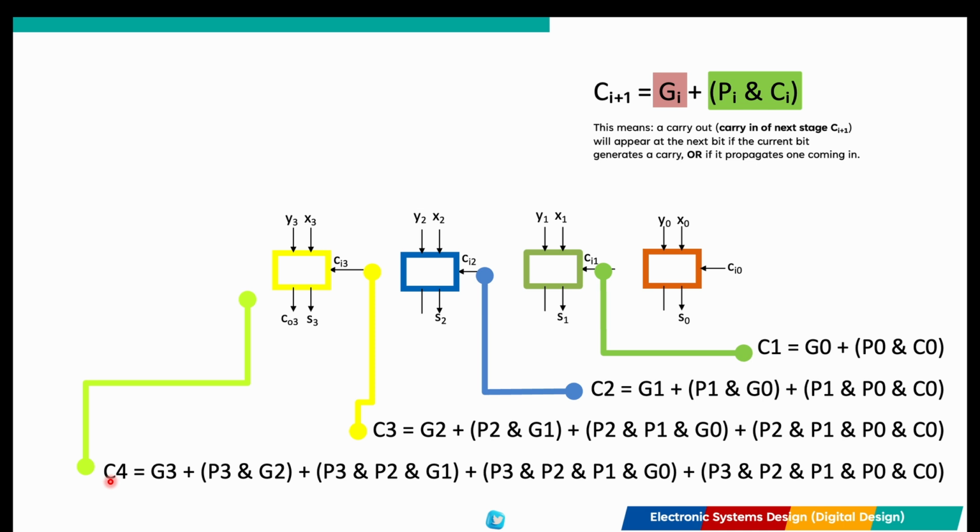Whether you are adding 4 bits or 32 bits, carry look-ahead logic ensures that the last carry is calculated almost as fast as the first carry. This is the core of performance-aware design. By spending more space on the FPGA to build these propagate and generate logic trees, we gain massive amounts of time by reducing propagation delay. This is how modern high-speed processors maintain their gigahertz clock speeds.